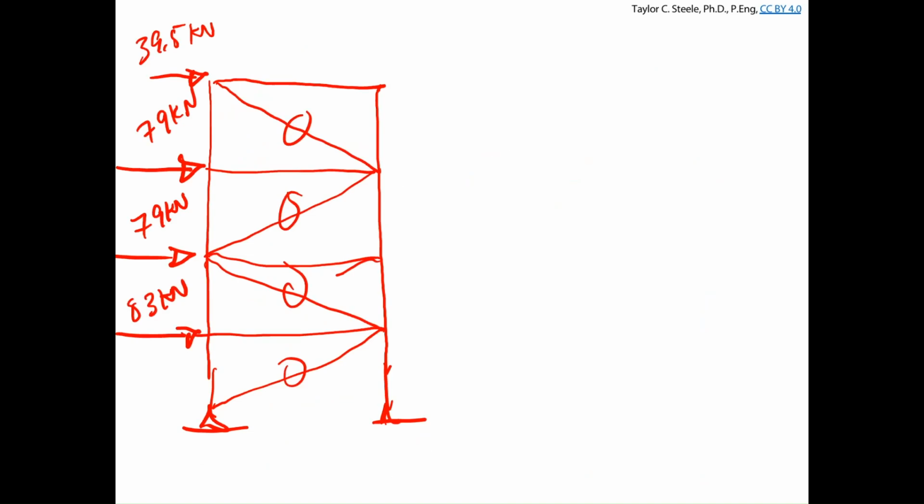Okay, so all of a sudden we're at a point where, if we idealize our brace frame system as an ideal truss and calculate the loads acting on these locations from the pressure coming in from the wall system, we can now go back to first year statics and figure out what these frame member forces might be. And the purpose of figuring out those forces is to figure out how big those braces need to be so that they're sufficiently strong to prevent them from failing under that applied load. Okay, any questions about that example or process before we wrap things up for the morning?